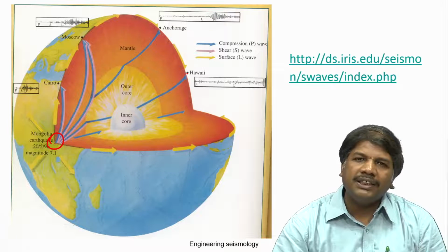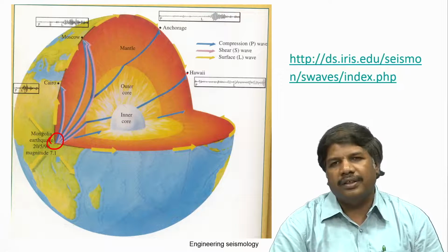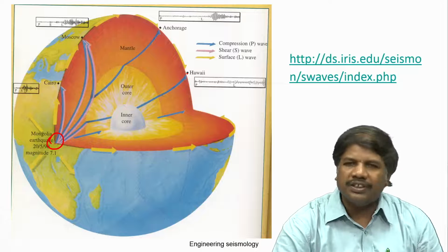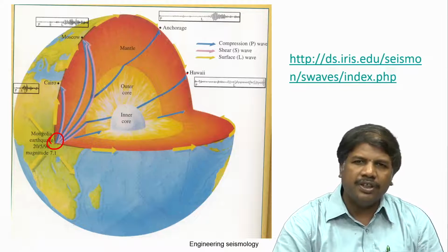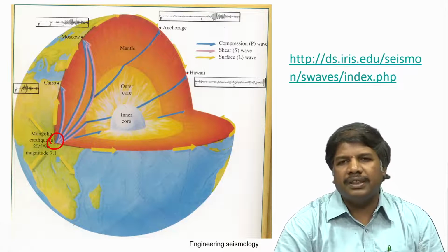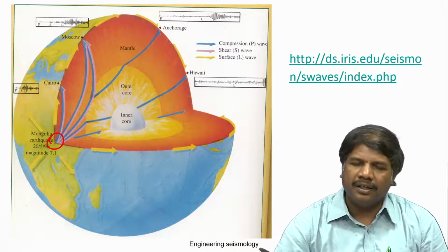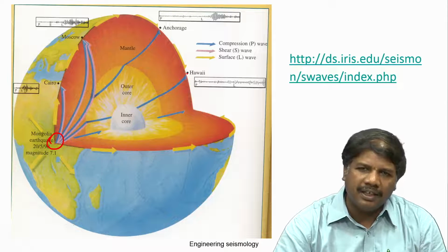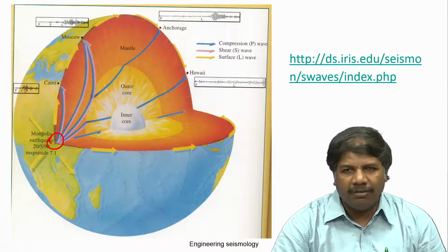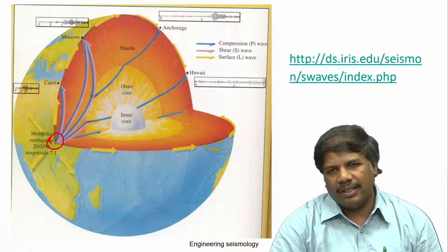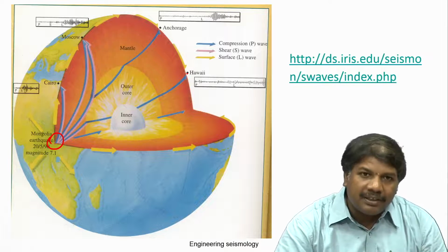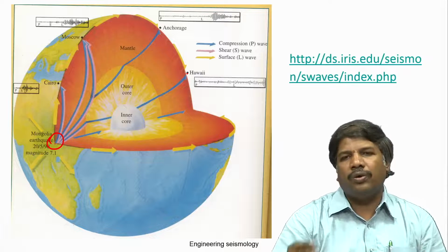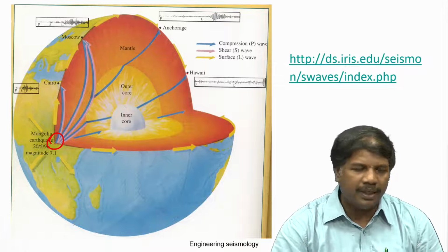Can it cause a crack to the building or not? Finally we found that it was a very negligible amount of vibration. So that vibration doesn't cause any crack in the building. Whatever crack he had, maybe it was a previous one that he noticed after the earthquake. That kind of suggestion and understanding requires you to know how the S wave and P wave propagate.